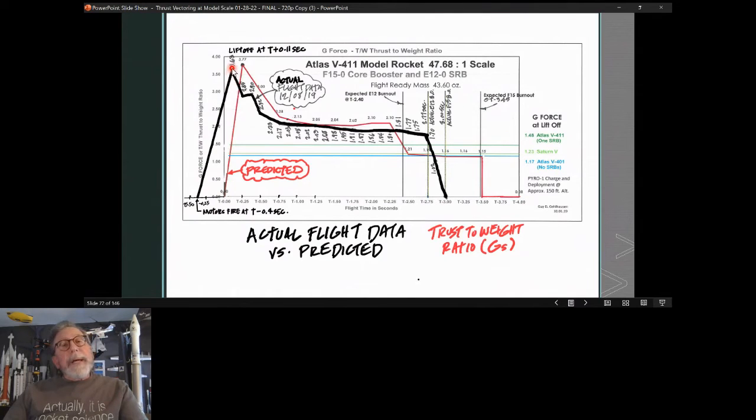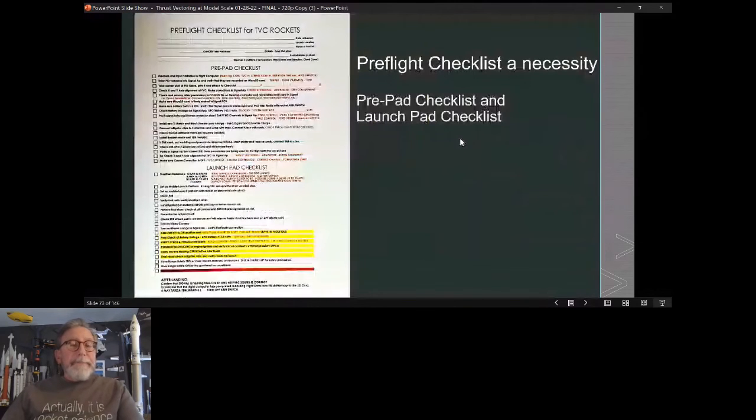So I did find out also that pretty consistently you need, at the high point of the initial thrust spike of a black powder motor, a thrust to weight ratio of around 3, and a sustained thrust to weight ratio of about 1.5 to get a rocket to fly. So that's about the best and closest you're going to ever get to mimicking a liquid fueled rocket with solid motors. I also figured out pretty quickly that I needed a checklist after screwing some things up.